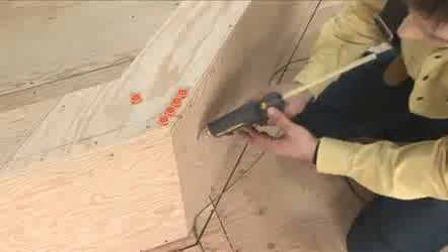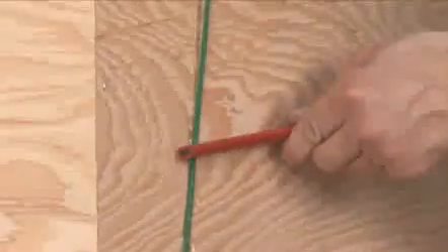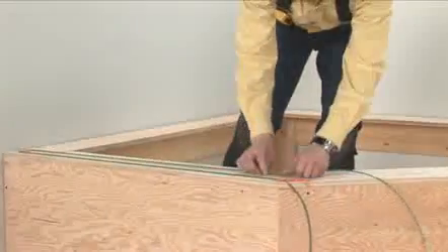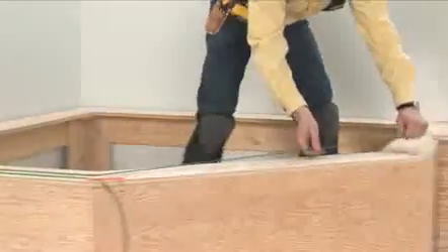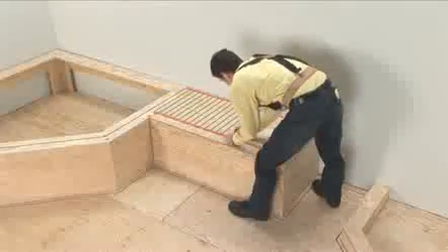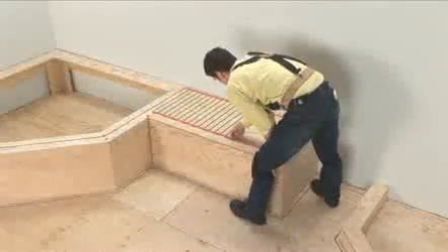If you have to install the cable on a step or podium riser, make a wide curve. This will allow for heat expansion and will avoid a tight angle that could damage the cable. You should groove the corner of the step or riser for the same reasons.